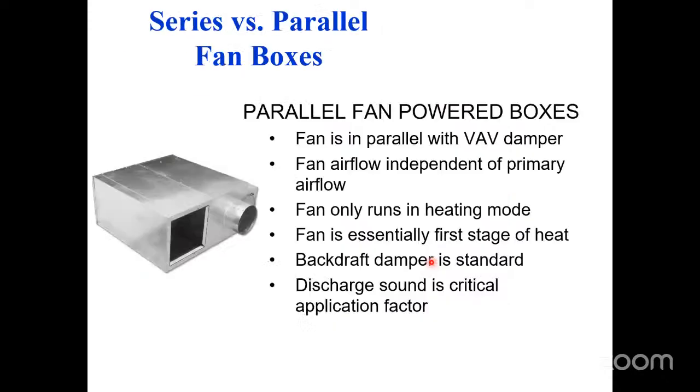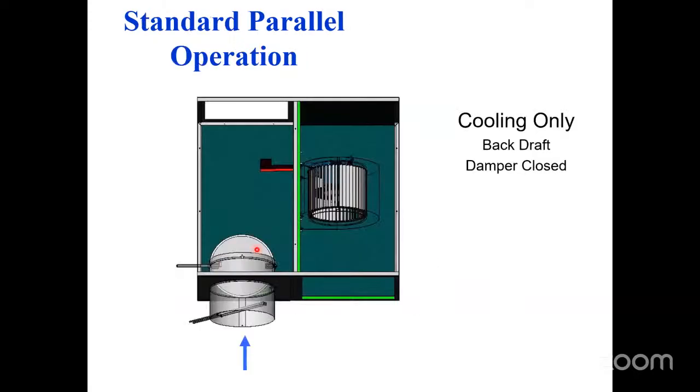The parallel fan power boxes, in contrast, previously my air handler was connected here and my fan was here in series. Now my fan is over here in parallel. I can pull air through this pathway without the fan being involved. I could not do that on series. Or I could pull air through this pathway with the fan.